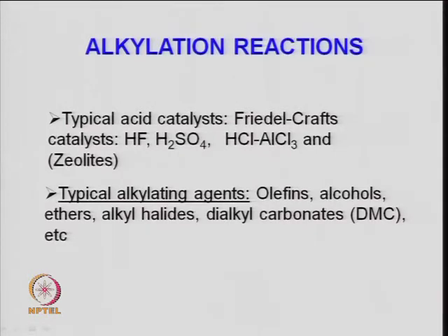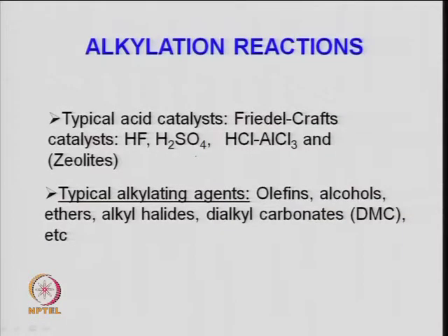Nowadays the trend is how to replace this hydrofluoric acid or sulfuric acid. For polymer gasoline, isobutene, an alkene, and an alkane can react to give a higher isooctane type of product. Again sulfuric acid is used as a catalyst. All these are highly acidic, so a different kind of material of construction is desired.